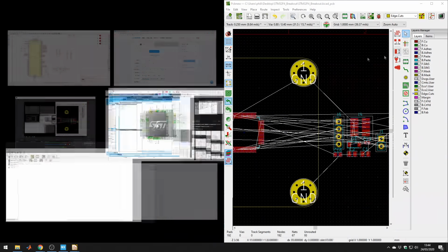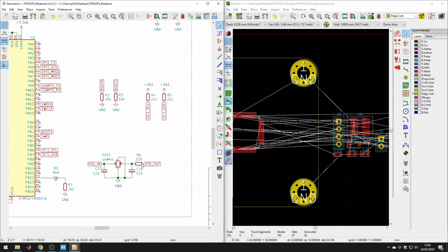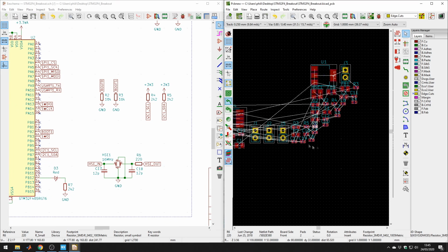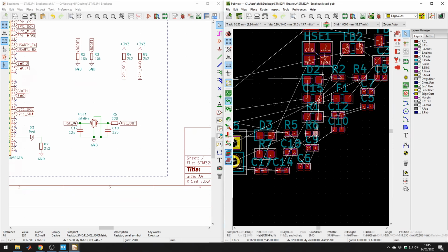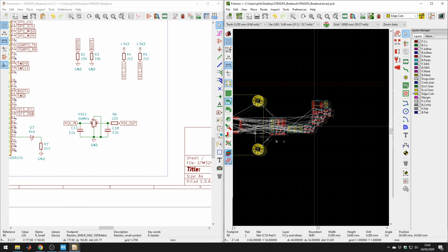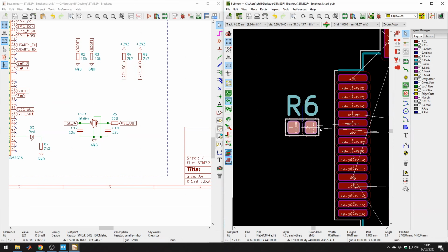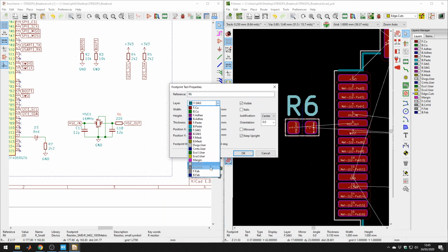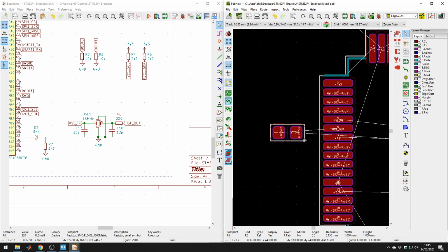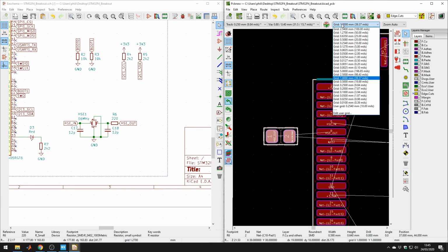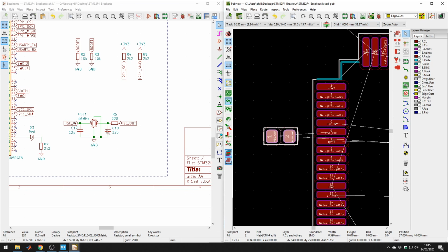So what you can do is put them next to each other, and if you click on one component in the schematic editor, it'll automatically snap to that in this right window, which is very useful. So that's what I tend to do. I have 2 screens, but I'm doing it on one now. So I move it in the general vicinity, get rid of the reference designator. So I move everything kind of roughly first, and then I change my grid and move it more precisely.